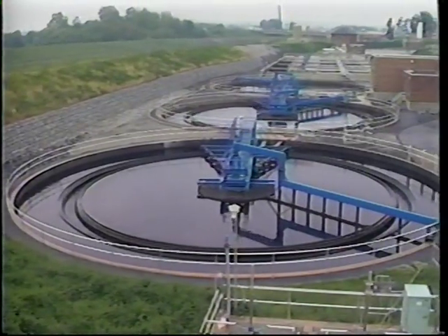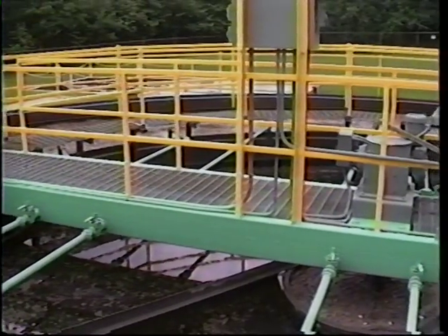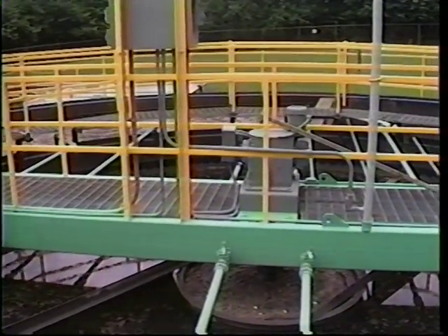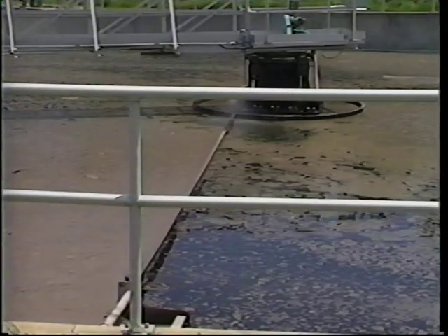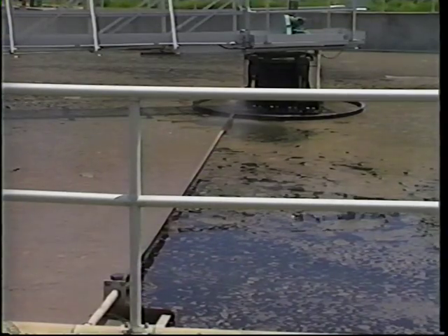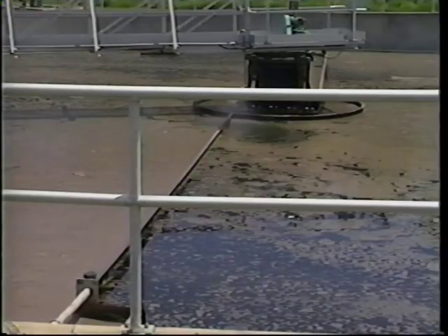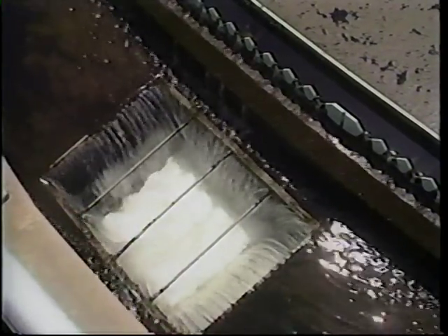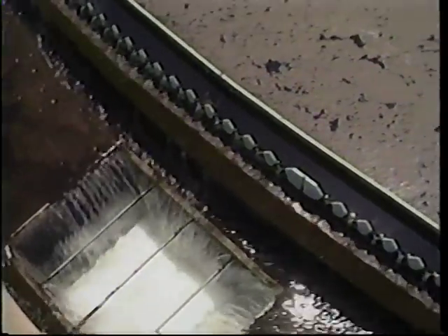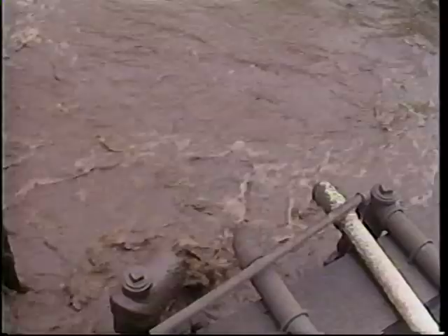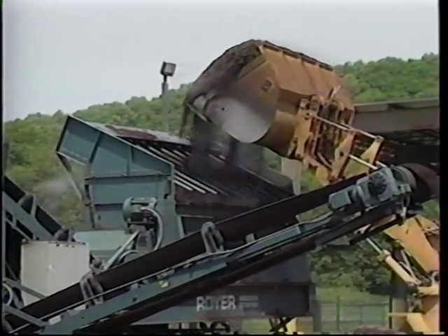Now, let's take a look at the final major component, the clarifier. This unit will usually be constructed of concrete or steel and may be round, square, or rectangular, depending on the design of the system. In the clarifier, the hungry activated sludge microorganisms are allowed to settle to the bottom while the clear, treated wastewater is decanted over effluent weirs. The settled microorganisms are then either returned to the aeration tank or disposed of as waste-activated sludge.